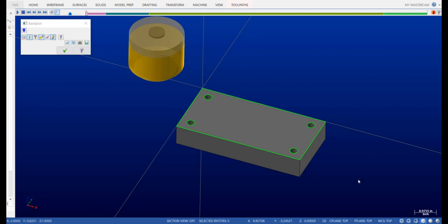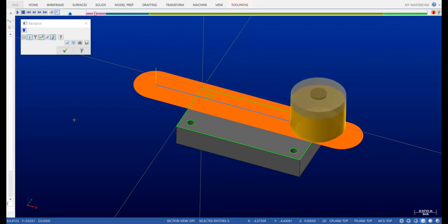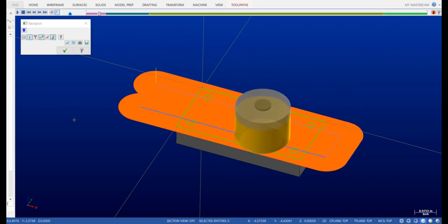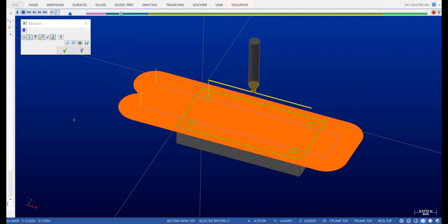Alright, in one of our previous lessons we talked about facing, center drilling, and tapping. And we wrote a program with multiple operations calling multiple tools, all for one part. But if you have a production run and you set up 4 different stations on the machine doing the same operation, you want to make sure that while the tool is out that you do the operation on each part.